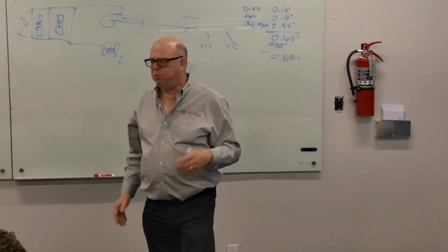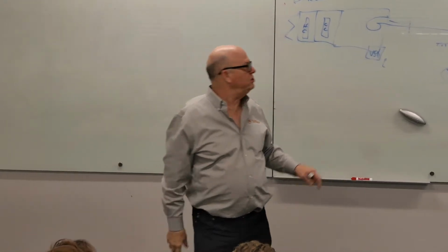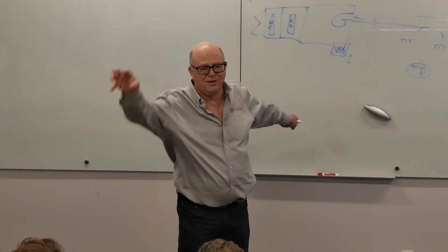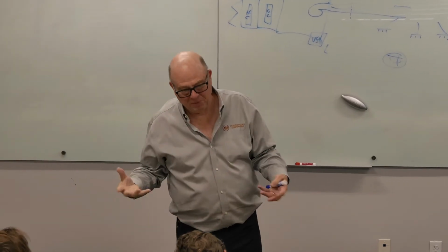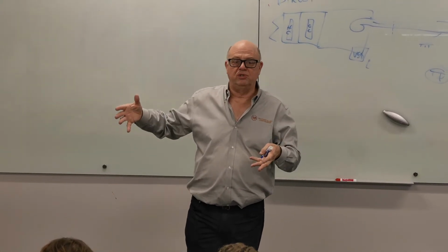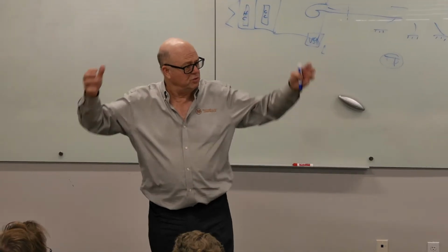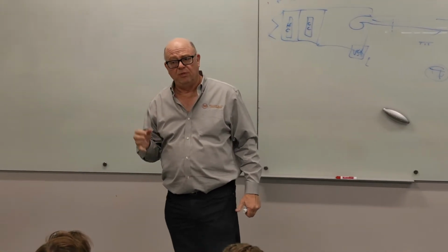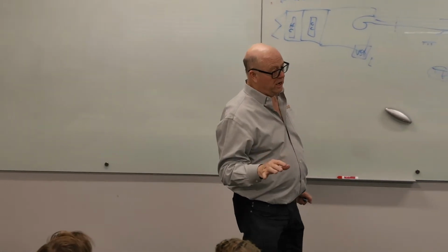So do you put in ductwork and VAV boxes, or do you just get a second single zone air handler for just the stage? And that's what people really do. And it's not just churches. I mean, any kind of a theater where your live performances are up on a stage with all those lights. And the light load with LEDs is not near what it used to be. It's a ton less, in fact.